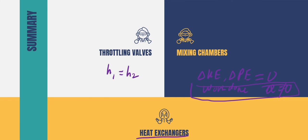For heat exchanger, kinetic energy and potential energy are also 0, and no work done, and obviously there is heat gain or heat loss from fluid 1 to fluid 2. So it leaves you with only H and Q, but you need to separate fluid A and fluid B in the mass balance.